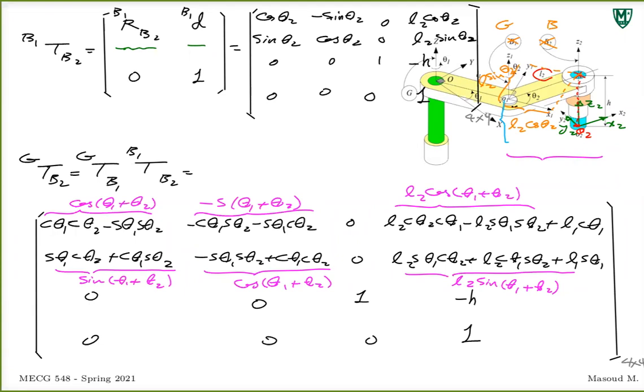Let's put it this way. It's almost never that obvious. But you will see later on that the equations for famous mechanisms are already derived. In so many cases, you just have to define the right coordinate frame. And if you do that, they say, well, with these coordinate frames for this SCARA robot arm, this is going to be the transformation matrix for you. In literature, not in this course, you're going to end up finding them, but generally they are available.